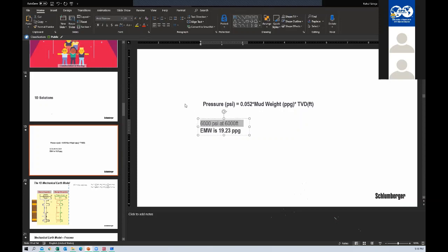You are trying to understand the logic, right? Why is it important, guys? Because when you are drilling a well, you have to decide the density of the mud. There you won't be able to measure the absolute pressures. You will only be able to modify the density of the mud that you are going to use, because at the end of the day, absolute pressure varies with depth. But density, you can keep constant, right?